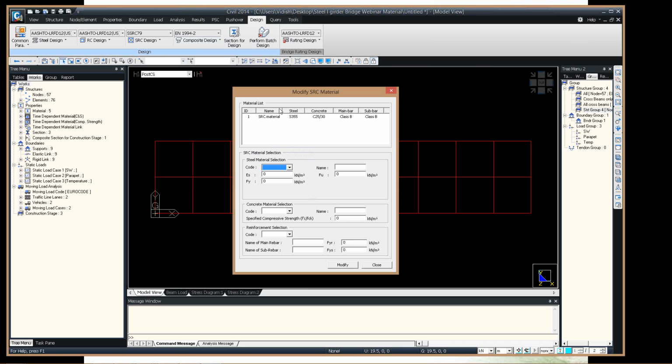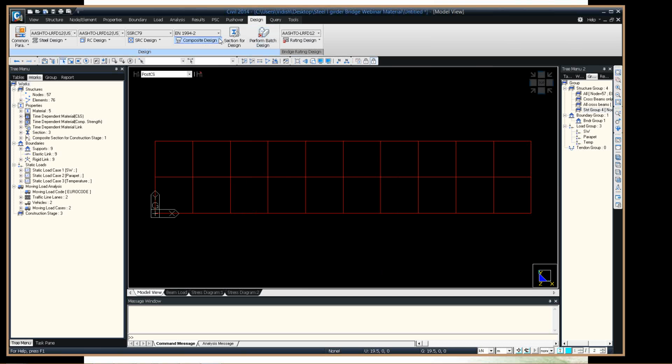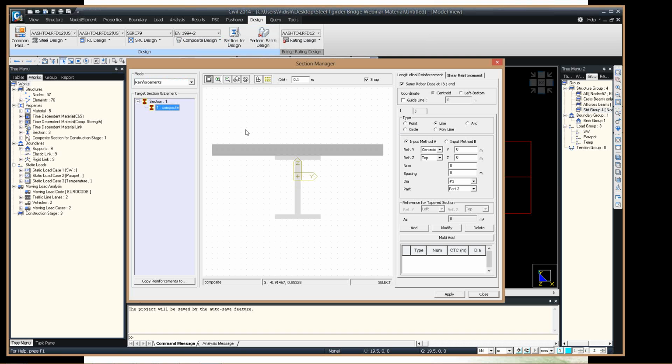The design material. So the material should be an SRC material, and here you can choose the design material. You can also choose user-defined material types if you do not want to go with a particular predefined material. So just define the reinforcement grade, and now we define some longitudinal reinforcements. For longitudinal reinforcement, we can very quickly and very easily define it. So let's say I want 15 bars of diameter 10, or let's say in this case diameter 14. So I begin to enter it like this. I'm just clicking and dragging my mouse, and I define it as an edge bar.